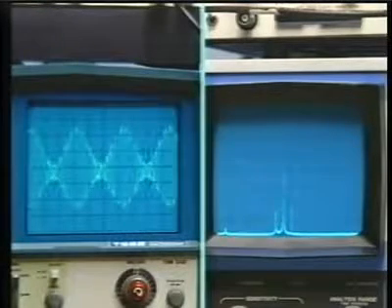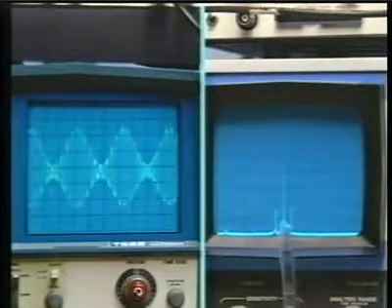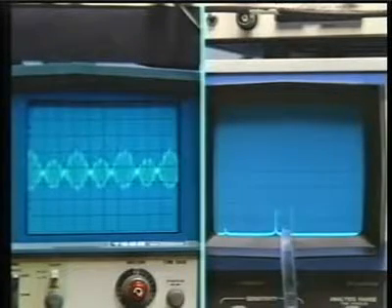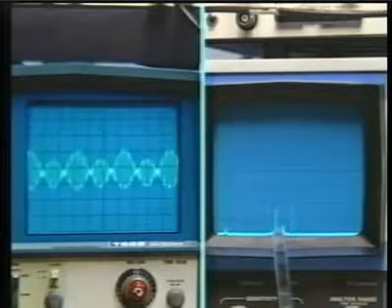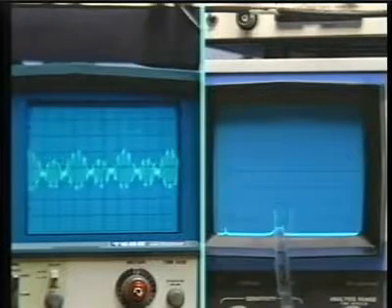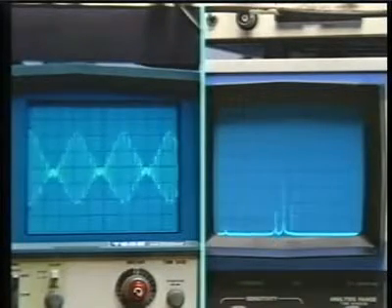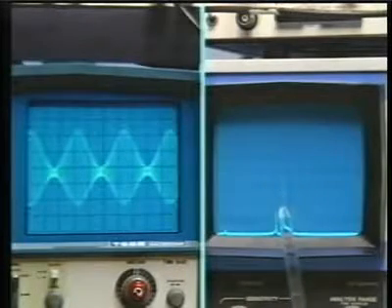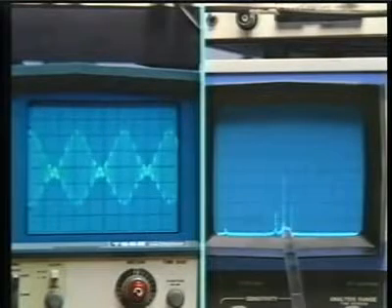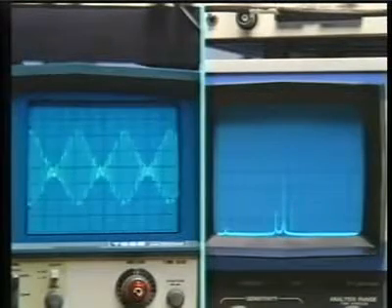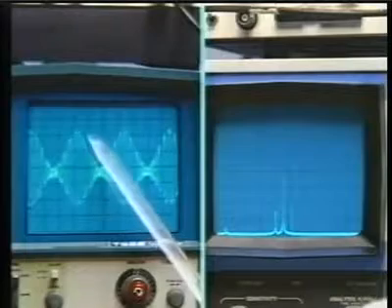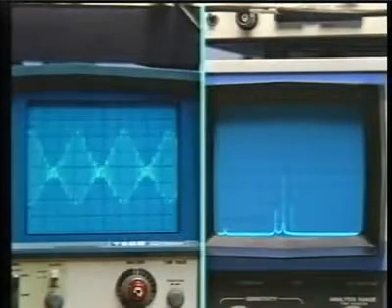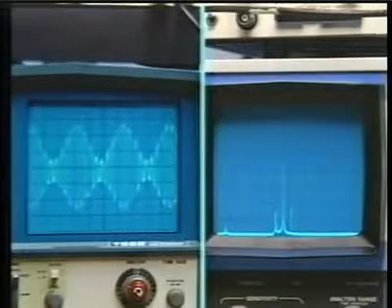Now, I had indicated previously, in previous lectures, that reducing the carrier is efficient in terms of power transmission, but requires a synchronous demodulator, whereas if there's carrier injected, as we have here, so that we're not overmodulating, the percent modulation is less than 100, then because of the shape of the time waveform, as you can see here, you can do the demodulation with a more or less simple envelope detector.